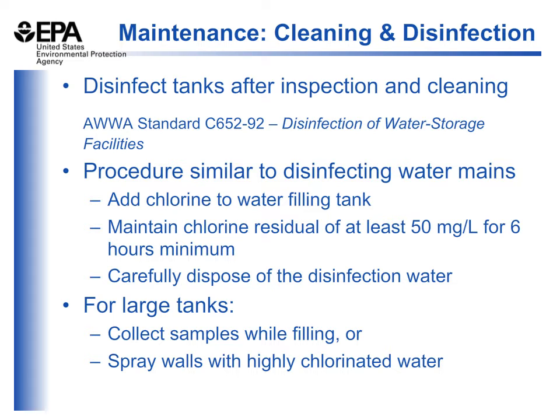Be aware of safety precautions. Whenever you're dealing with chlorine, you're going to want to make sure that the operators who are doing the spraying are wearing a self-contained breathing apparatus, because the chlorine fumes of the spray water can be hazardous.